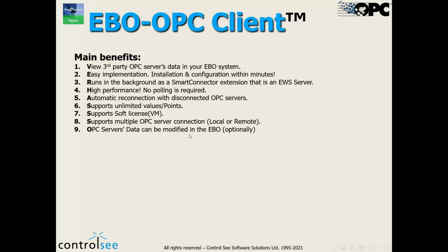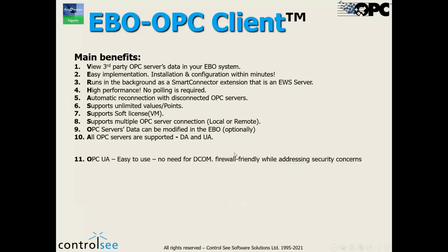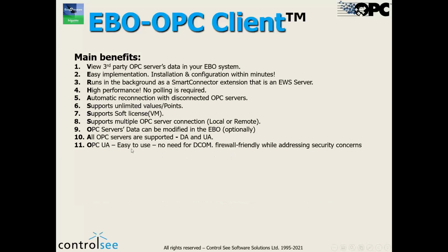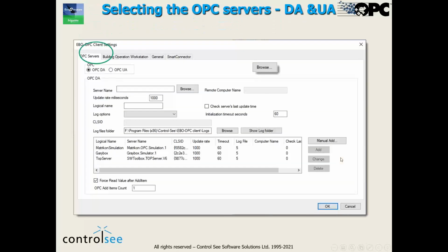OPC servers data can be modified in the EBO optionally. All OPC servers are supported, both DA and UA. OPC UA is easy to use, no need for DCOM, firewall friendly while addressing security concerns. And now we can see how this is done, how this is configured.